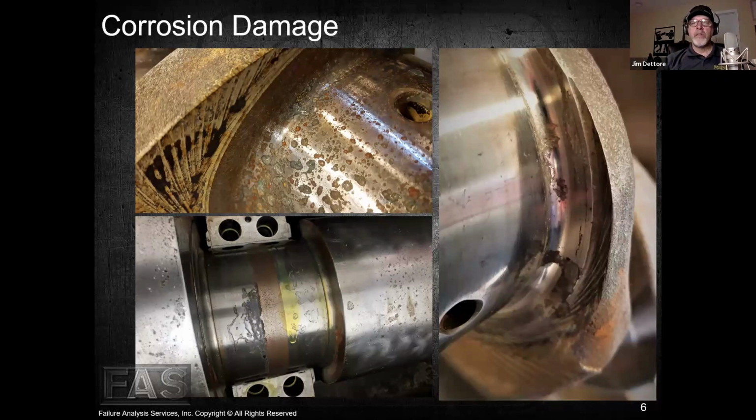When they pull this engine out of storage, if it's already been rebuilt or it's low hours, they don't tear it down completely. They do some checks on it, they change oils, they replace a few things, and they start going back together with it. Sometimes it gets missed that the exhaust was open and that we had water intrusion, right? But it drips on the crankshaft and it becomes the electrolyte that starts to corrode the steel.